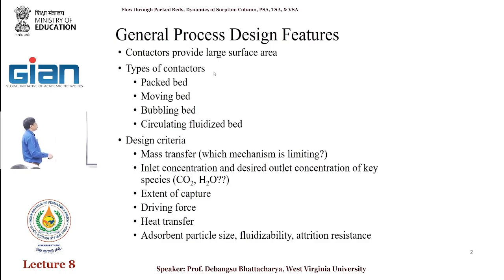Then the other thing is adsorbent particle size, which is a very important thing. So what should be the particle size? When we do it at lab scale, it's often in the form of a powder, right? Now when you take it to a fixed bed in real life, you cannot use a powder in a pressure swing adsorption or anything. The entire material will be carried away with the gas. So you have to have a particle size that will make it stay inside the bed.